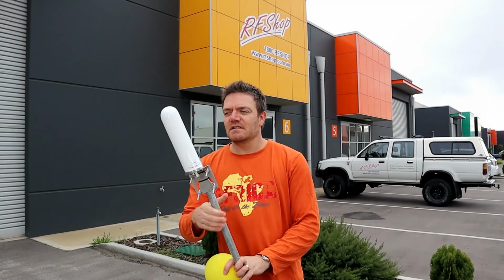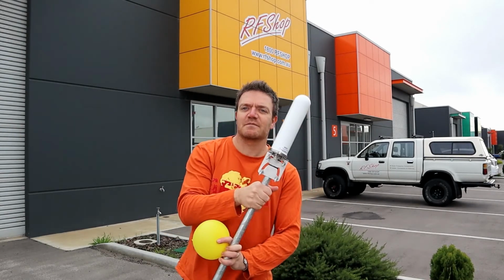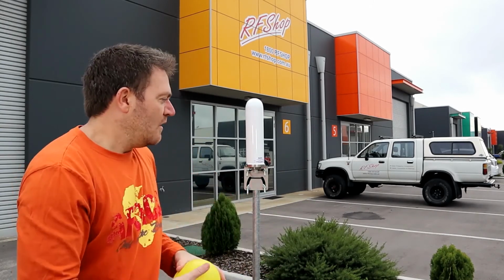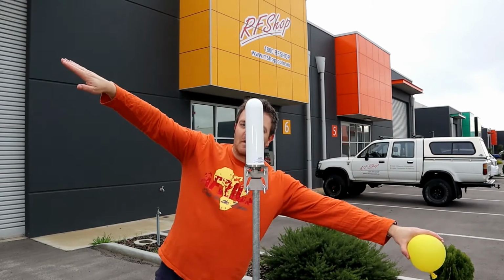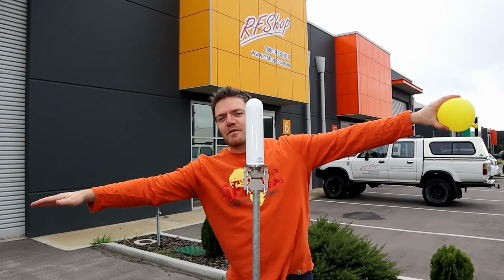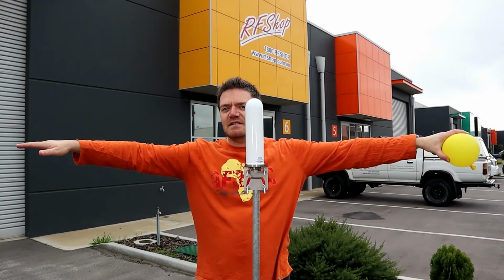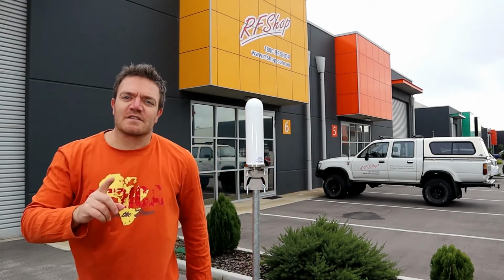If it goes like this, you still have something on the horizon, so it doesn't matter if the antenna isn't properly aligned. If you have a high gain antenna, so very flat, like a disc, a cone like this, when you start to move around up and down like this, you lose the target. So when it's a high gain antenna, a nice beam like this, once the antenna stands like this, there's nothing on the horizon anymore. So it's not always to say bigger is better, high gain is better than lower gain. You need to look at the actual application before you make your final decision.